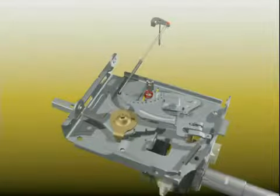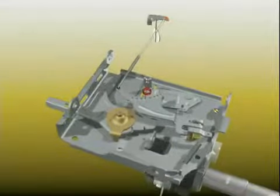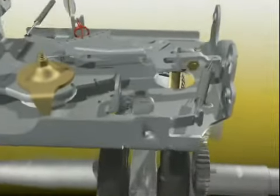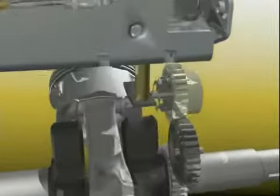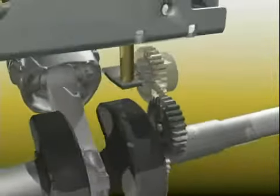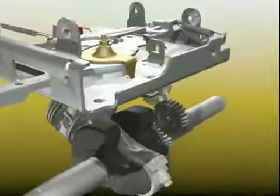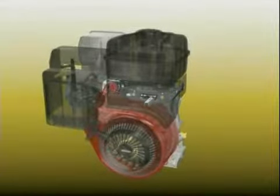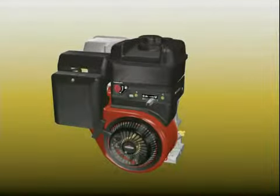Mechanical governor systems have internal and external components. It's fairly common to assume, often wrongly, that an overspeed problem is the fault of internal engine components. To examine the governor gear assembly for faults usually requires that the engine be removed from the equipment and disassembled. Follow this procedure to isolate the problem as internal or external.